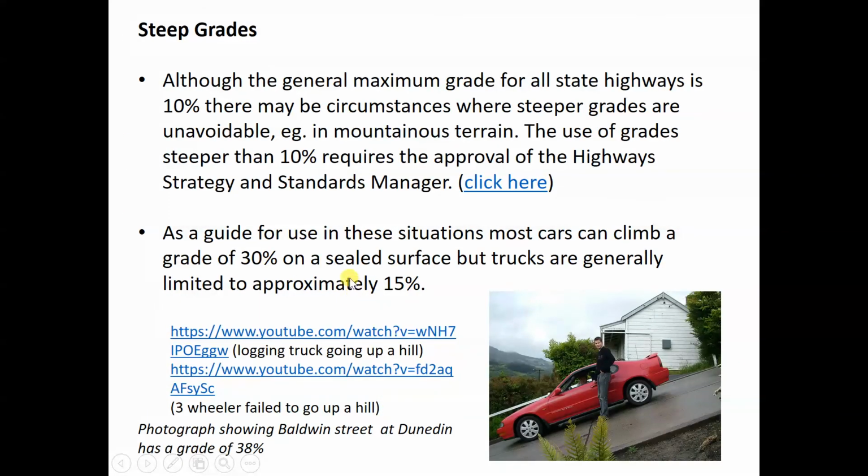Steep grades. Although the general maximum grade for all state highways is 10%, there may be circumstances where steeper grades are unavoidable, for example in mountainous terrains. The use of grades steeper than 10% requires approval of the state highways strategies and standards managers.